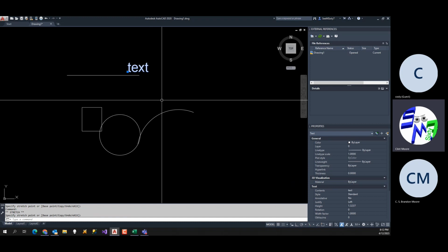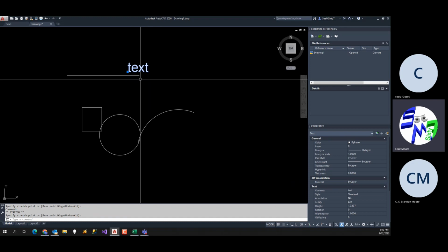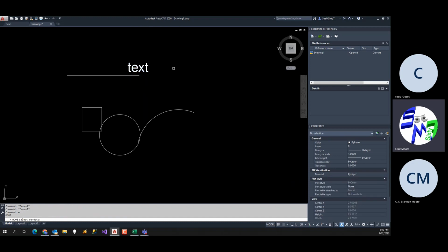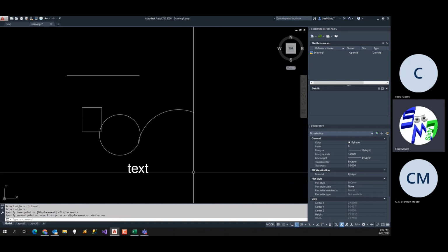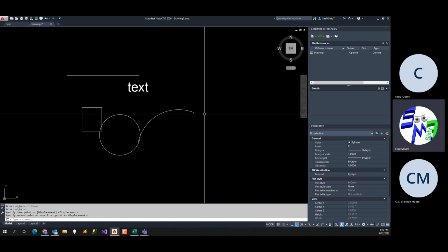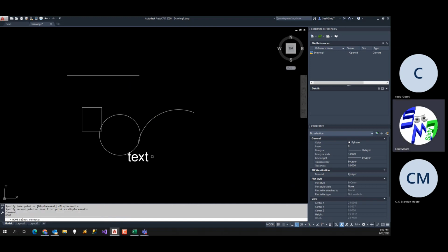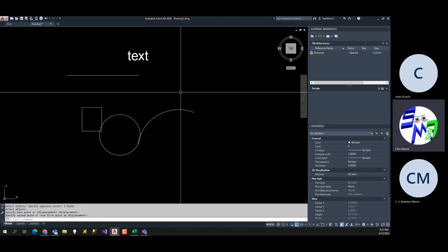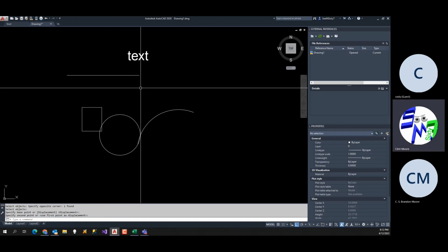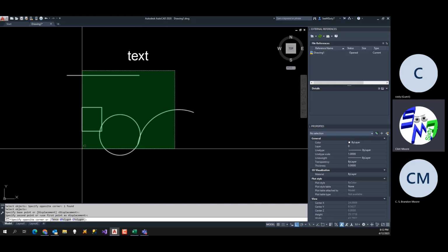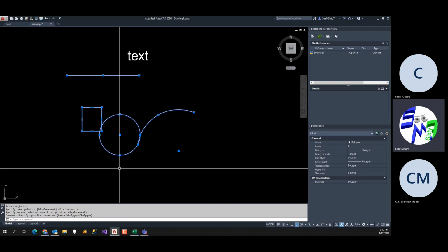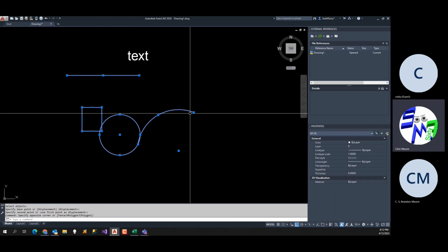Okay, and if you're using Snap and a good setup drawing, you don't necessarily have to grab things on the item. So if I wanted to move this thing and I wanted to go straight down, I just make sure ortho's on, I'm here, and I move it down. I don't have to be anywhere near it to pick. Okay, gives me the ability to grab, boom. I can crossing that, boom. I can window it. Okay, these are the things you're going to get used to when you're doing the job. All right. Again, selecting things, crossing. If you don't have a command active, you just drag, you go to crossing. You notice all the grips coming up. That tells you no command is active.